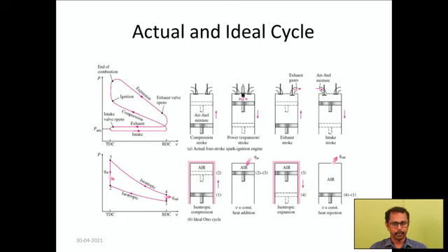And the power stroke. In the power stroke, the highly compressed air fuel mixture will be ignited by the spark plug. The spark plug creates a spark and it ignites the air fuel mixture. This ignition produces very high pressure and temperature. These high pressure and temperature burnt gases push the piston down, so that the piston moves from top dead center to bottom dead center.